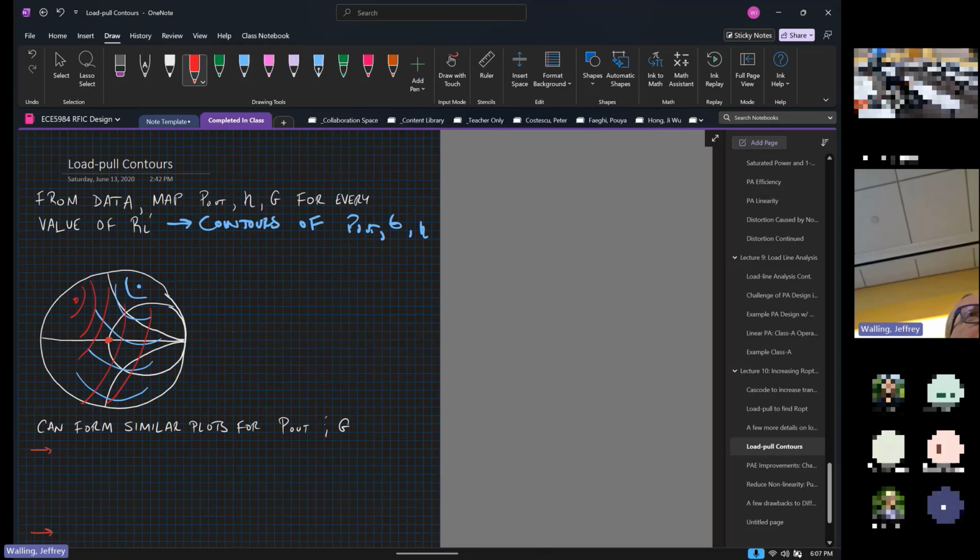I'm sure that there's some case where it isn't. But for instance, if the device has a lot of parasitic inductance due to bonding wires or something like that. Now, for our devices that we're going to be doing load pulls for, they're just going to look capacitive because, unless you add the bond wire inductance to the simulation, it's not going to be there. Yeah.